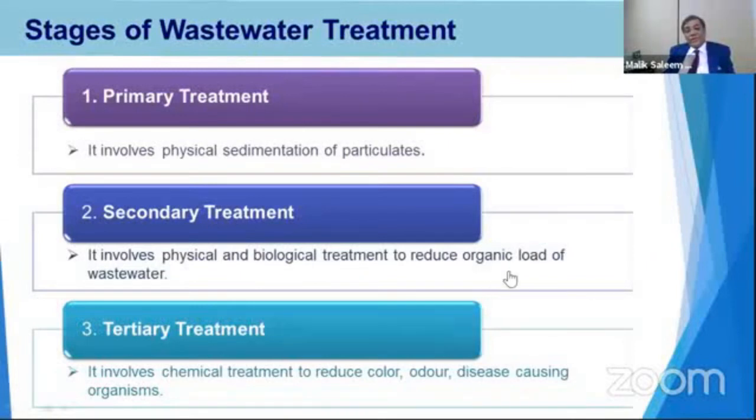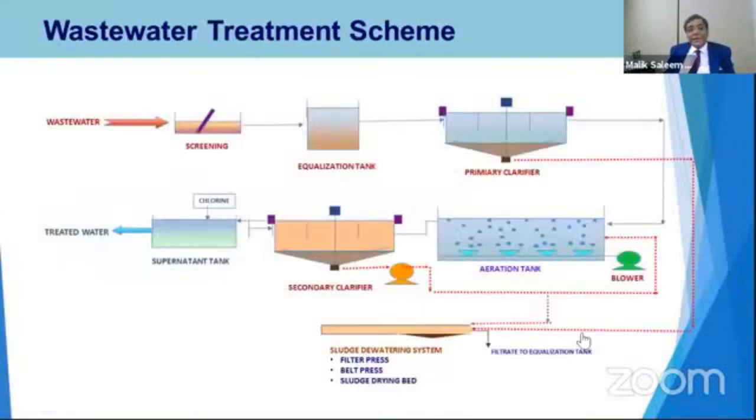that is also disinfection, chlorination, removal of suspended solids by sand filter, multimedia filter, or improving the color by incorporating activated carbon filters. Inshallah, we will discuss that as well in detail.